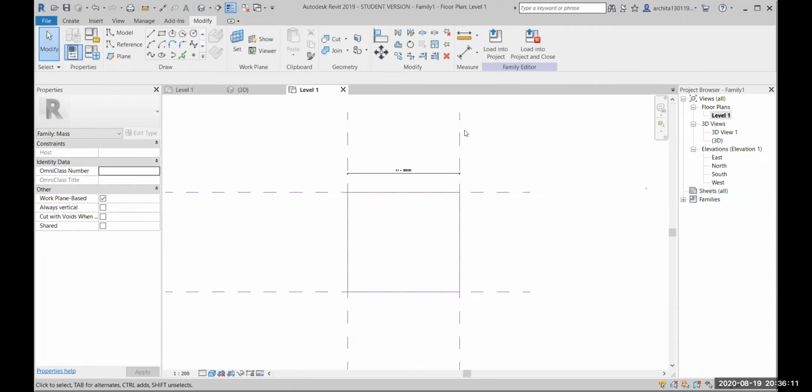You're not satisfying the constraint. Did you do the exact same thing? I'm sure you might have, by mistake, clicked on the lock, and that's why it's not moving properly. It happens. You just have to be careful while you're doing it.